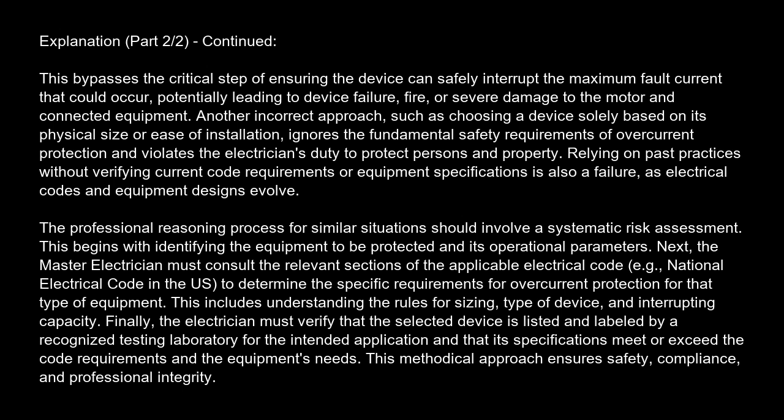Finally, the electrician must verify that the selected device is listed and labeled by a recognized testing laboratory for the intended application, and that its specifications meet or exceed the code requirements and the equipment's needs. This methodical approach ensures safety, compliance, and professional integrity.